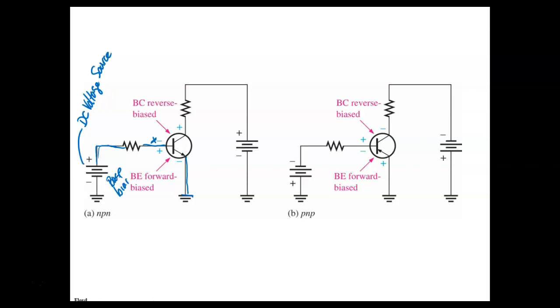Now we know this power supply right here, if it's plus 5, which we're going to have to do to be able to control it a little better, and later on we'll learn how to make this better. But if this is plus 5 when we forward bias the P-N junction, we would have a short circuit, right? So the purpose of this resistor right here, if this is 5, then we've got to put a resistor in there to drop 4.3 volts, right? This is silicon.